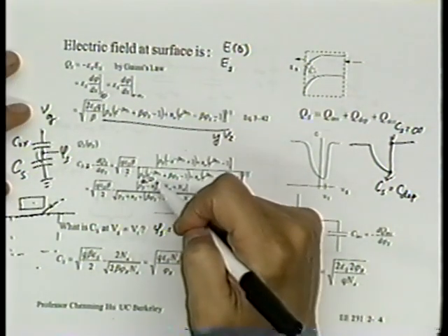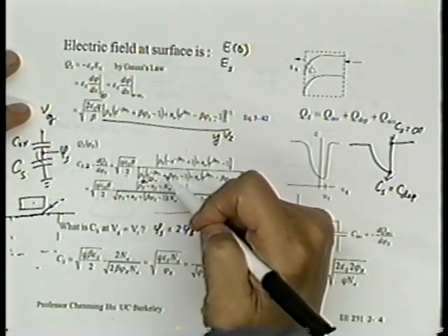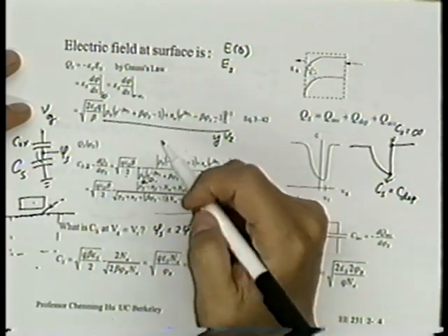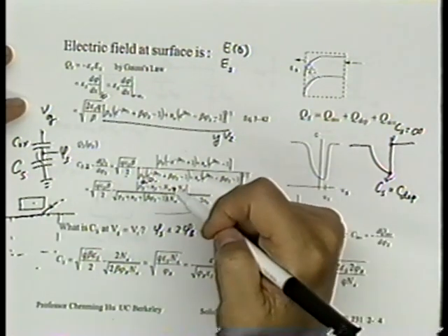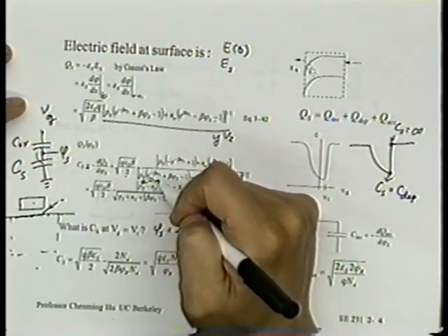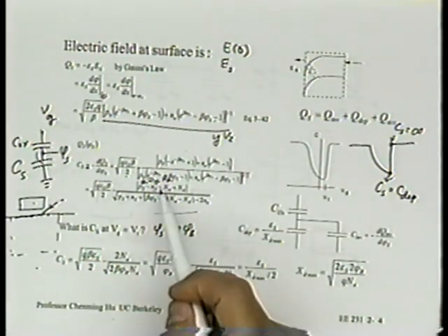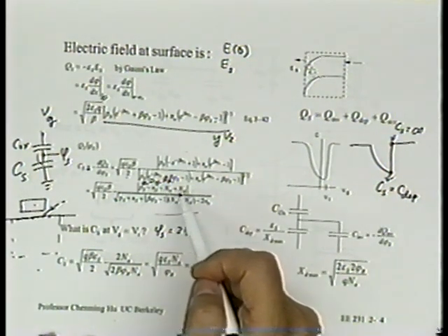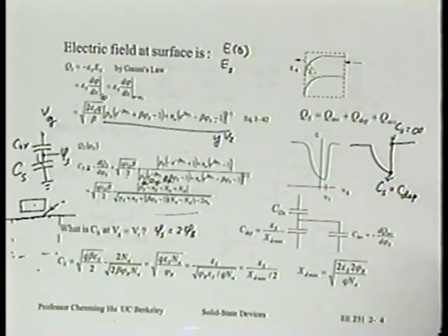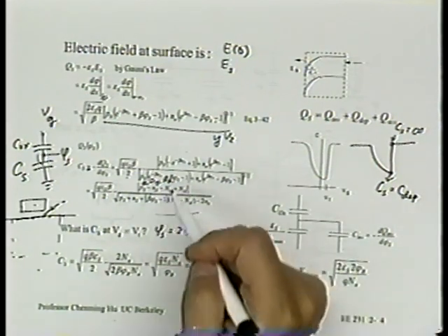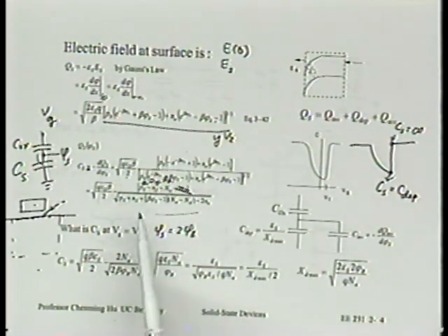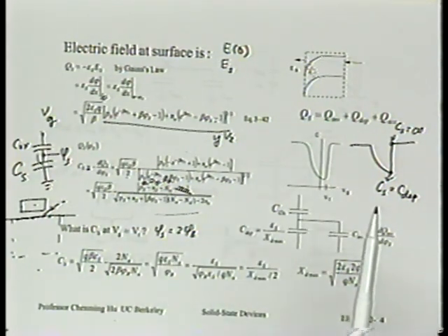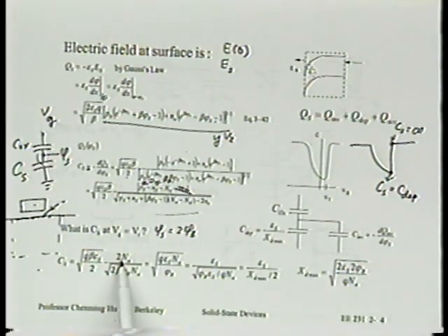Yes? And what is NS approximately equal to? Okay, roughly equal to NA. Is that right? Very good. And let's keep the problem simple, saying there's only acceptor in the substrate. There are no donors, because we're using P-type as the example. Is that correct? So just take this away. So the numerator becomes what? Minus NA minus NA, in other words, minus 2NA. Is that correct? So do you see where we get 2NA here?